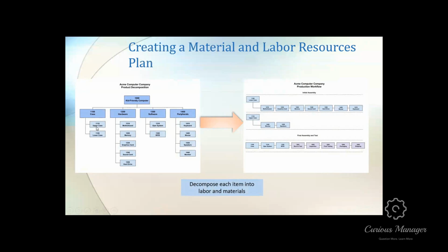Now, when we do this, basically, we will decompose our components down to the lowest level, down to the screw or the nut or the gasket or whatever, okay? Usually it goes down to the consumable levels. The consumables are the lowest level, and then the next level higher is the first level repairable or the first level main part. So you've got different levels of assembly.